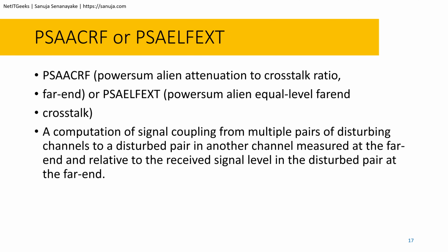PSA ACRF or PSA FEXT basically is a Powersum alien attenuation crosstalk ratio far end, or the other one is a Powersum alien equal level far end crosstalk. It's a computation of signal coupling from multiple pairs of disturbing channels to a disturbed pair in another channel, measured at the far end and relative to the received signal level in the disturbed pair at the far end. So again, at least remember these definitions.